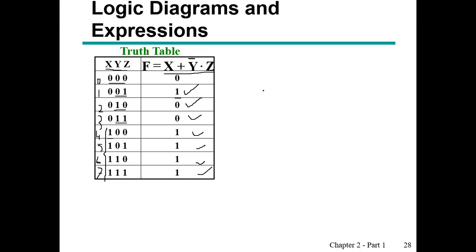Now we can also create a logic diagram for it. So how can you create a logic diagram? If you look, this function is basically the OR of what? This is our function f. It is the OR of x. Say this is our input x, and x is ORed with what? It is ORed with y prime and z. So we need to calculate something like this.